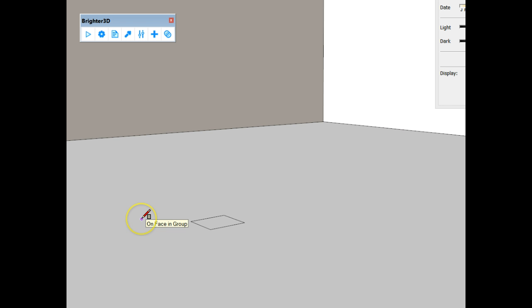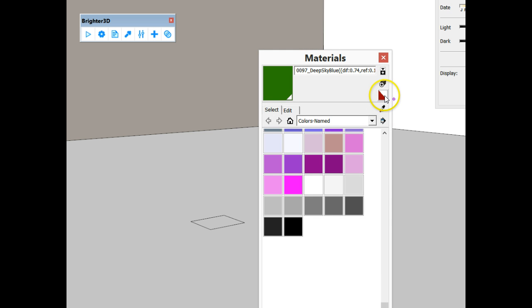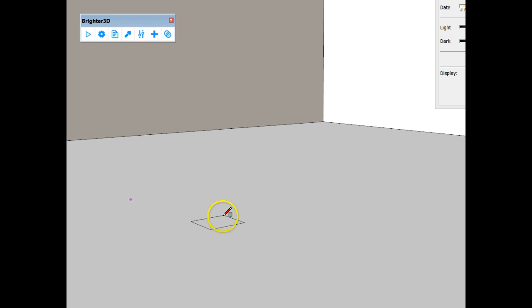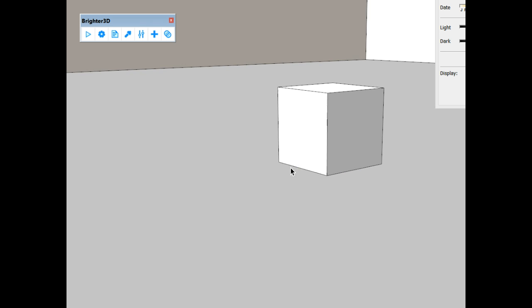And as you can see, I've got two sides of my faces already set up in styles. I've got a red and a white, and I put my back faces red so I can turn them around. When you're doing rendering, you have to have the faces all facing the camera, and the back faces have to be all facing away or internally. So let's put in 50 for the height of that, and 50. So we've got our cube, and let's zoom in here now.